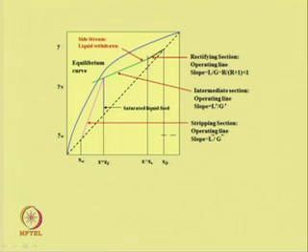This is the operating line for the stripping section, and this is the operating line for the intermediate section, where it intersects at x is equal to x s at these locations, and then this is the feed condition Z f, and it intersects at this location since it is a saturated feed.